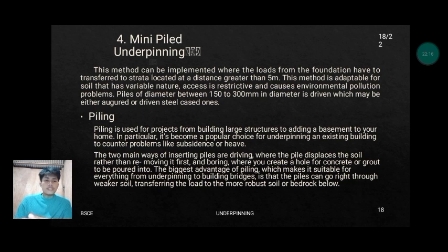The two main ways of installing piles are driving, where the piles displace the soil rather than removing it first, and boring. The biggest advantage of piling, which makes it suitable for everything from underpinning to building bridges, is that the piles can go right through weaker soil, transferring the loads to the more robust soil or bedrock below.